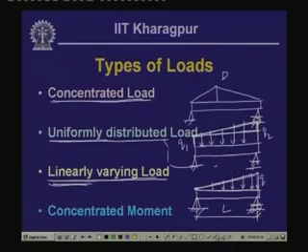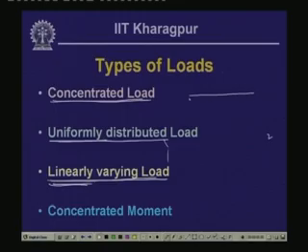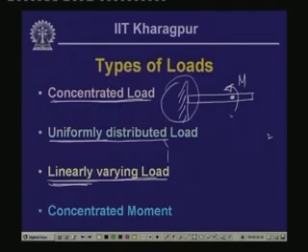Now, many times other than this distributed loading or concentrated loading, we get loading in the form of a concentrated moment. Let us say that we have a cantilever beam which is fixed at this end. Now, at a particular point in the beam, this beam is subjected to a moment m at this point. This will generate reactive forces because of the application of this moment, and this kind of loading we call a concentrated moment.